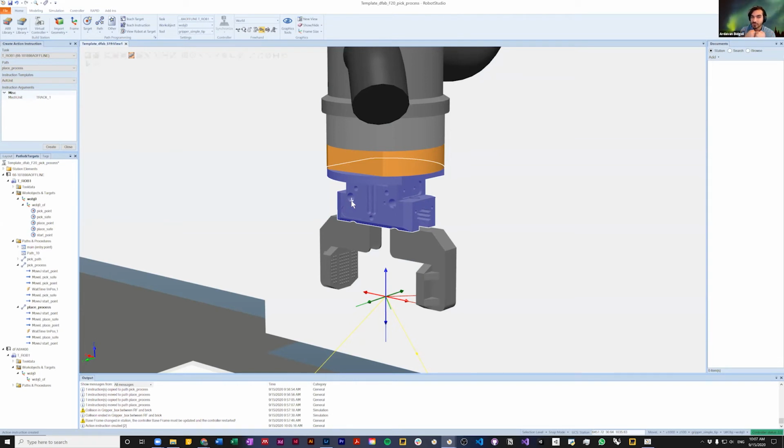And they are always forcefully doing it. So for example, if you try to hold it by hand and open it, it's going to actually push your hands. Or if you try to stop it from closing, it's going to add a lot of pressure. And the safety alert: never try to stop these things with your hand. Never try to stop them with anything, because they are industrial grade tools and they're really powerful.